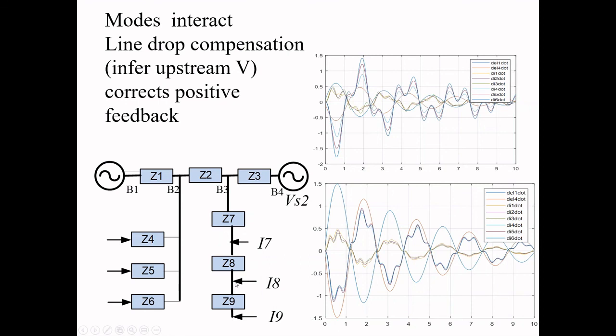I mean, if inverter 8 was a source of voltage that we tell an angle to, right? A grid forming inverter chooses a voltage and chooses an angle. And oftentimes the angle updates are based on power flows, so it can pretend to be a synchronous machine. But you can see that we're introducing a new set of synchronous machine oscillations potentially by using grid forming. Doesn't mean that we can't broadcast a reference angle for the grid forming to actually track. And I think that would then bring them into the fold as being stable local oscillations.